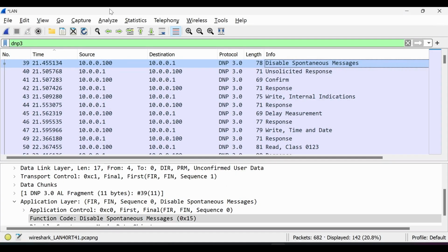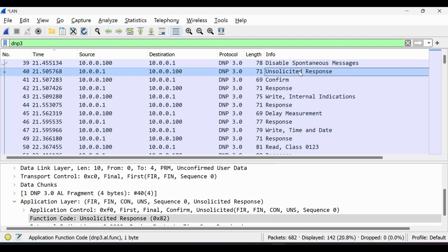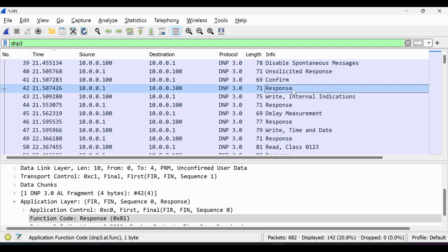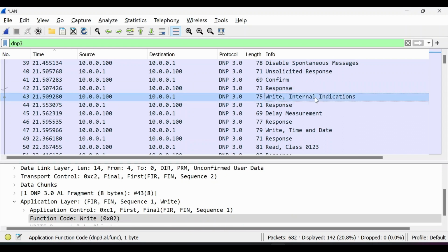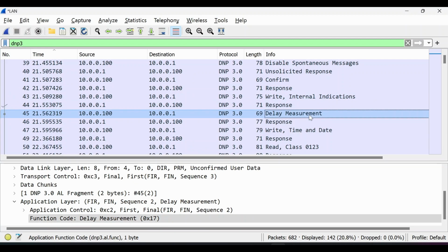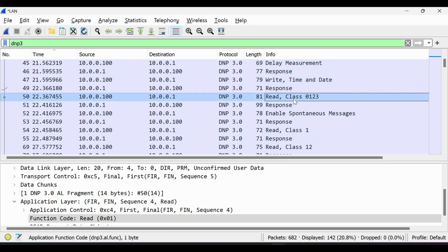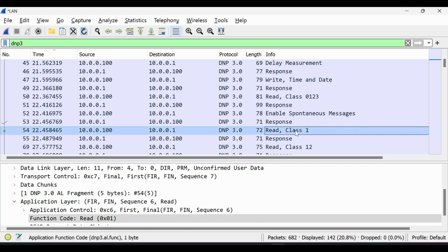While we were performing the SCADA test, I had Wireshark running and capturing packets. I've got a filter to show DNP3 traffic only, so we can review communication between the SCADA, which is 10.0.0.100, and RTU behind the router, which is represented by 10.0.0.1. There are several function codes used during the initial connection. We need to know them in order to set up a proper policy later.